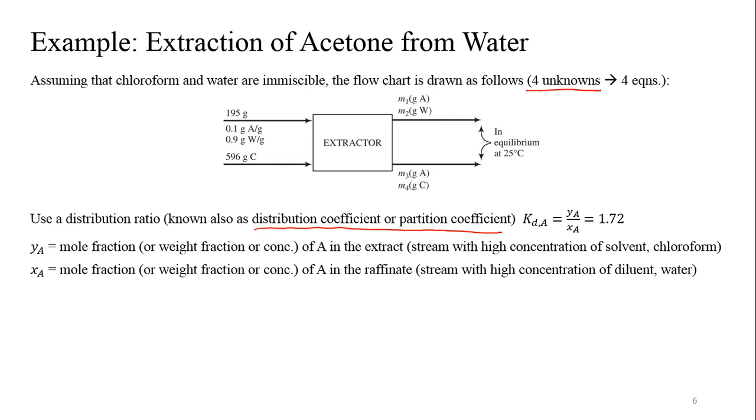We do mass balances of some form, right? Okay. So with these components, then we could do at least 3 mass balances. And then we're going to need a 4th relationship. Where does the 4th relationship come from? Yeah, it comes from the equilibrium condition with the partition coefficient.